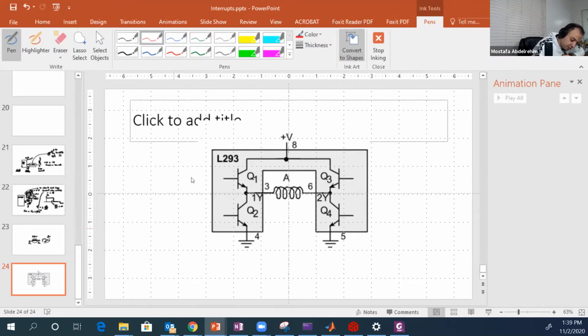If you put 1 in Q1 here, or high voltage, let's say high, and high in Q4, and low or 0 on Q3 and Q2, so this guy will be off, this guy will be off, and you will have a current flowing in that direction from the source here. The current will flow in that direction, like this.